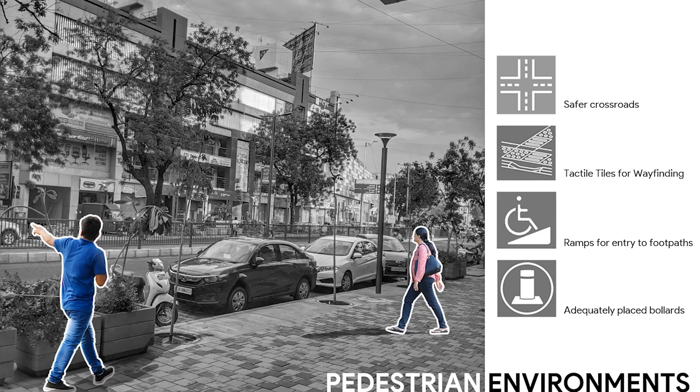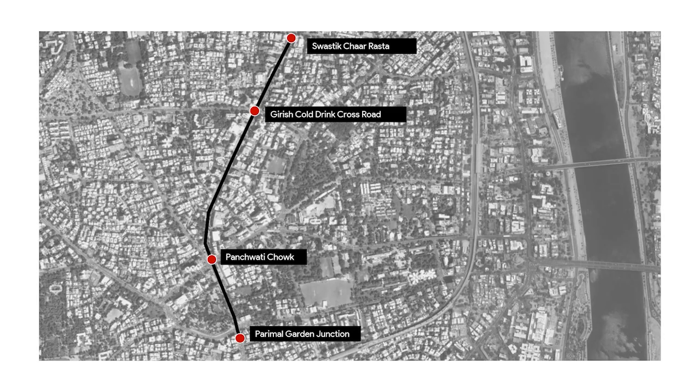The main components of the pedestrian environment are: 1. Safe crossroads, 2. Tabletop crossing wherever necessary for slow movement of vehicles, 3. Tactile tiles for guiding, ramps for the entry to footpaths with proper slope, and 4. Adequately placed bollards with aligned tactile and wheelchair access gap.